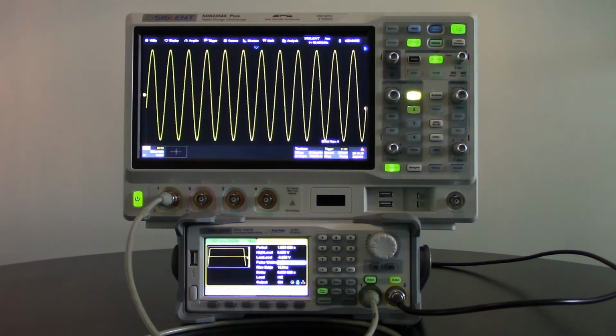This particular application, they wanted to capture when that voltage dropped to a certain level, but they needed to see it in a very long time base. So this particular customer wanted to collect data for seconds and take a look at single events that may have dropped out. So here in the US or North America, our power is 60 hertz. That means the period of the sine wave for the power or the voltage being delivered is 16.67 milliseconds.